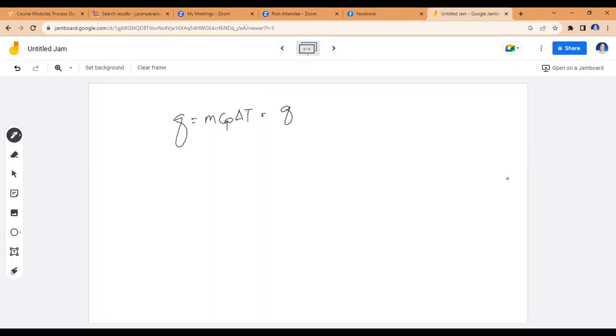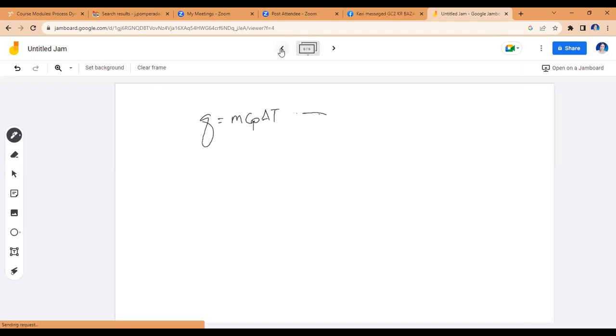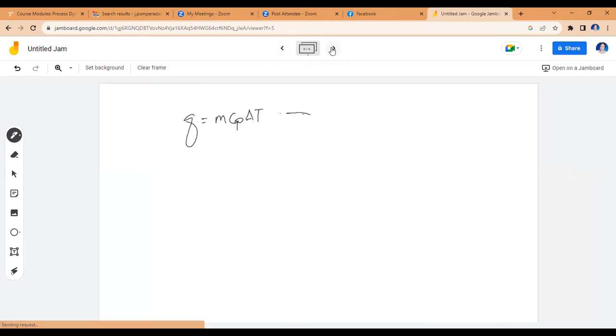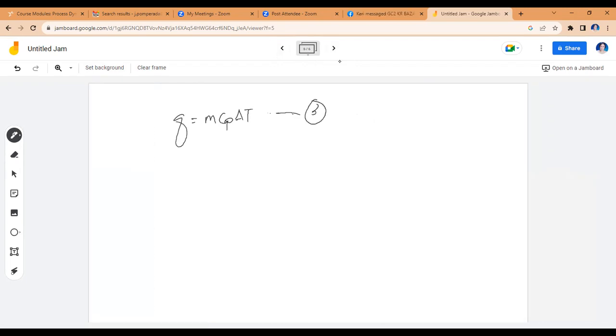Okay, I'll just have this one. You have this formula Q. So this is our third equation already. And actually, the Q that you have here is the same Q that you will be getting here in the heat flux, which is hL delta T, if we're going to consider convective heat transfer. So this is the fourth. So we're first going to determine the Q here, and we're going to place it in there.